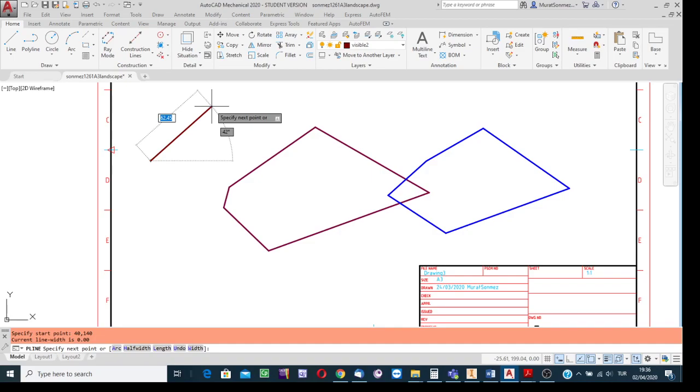I know the delta x value, I don't know the inclination angle, I know the delta y value. By delta x and delta y, I mean, to repeat again, the shortest distance between the terminal points in the x and y directions. Say that the delta x value is 50. I wrote 50. And now, to be able to teach the software that this number is not the length of the line but delta x, it is a trick.